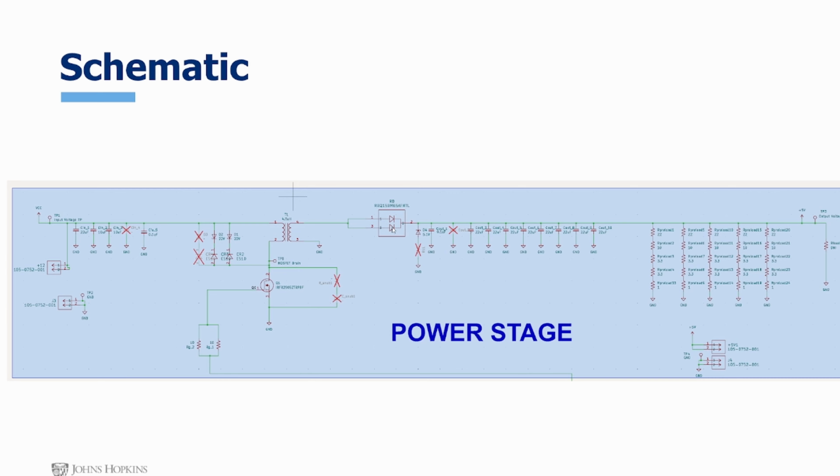The diode rectifier RBQ15BM is shown here. Our soft clamp at 5.1 volts is shown here. And our output capacitors are shown here as well, and the preload resistance network used to achieve around 8 ohms. At 10 ohms, the converter was going into DCM, so 8 ohms was selected so that the converter would remain in CCM. At the bottom here, we have our output connector.